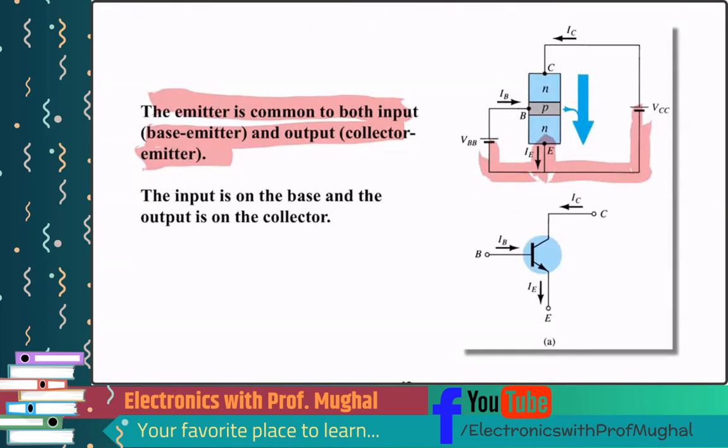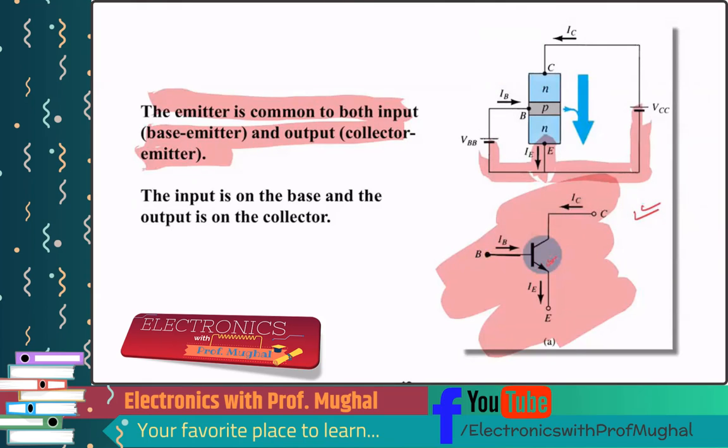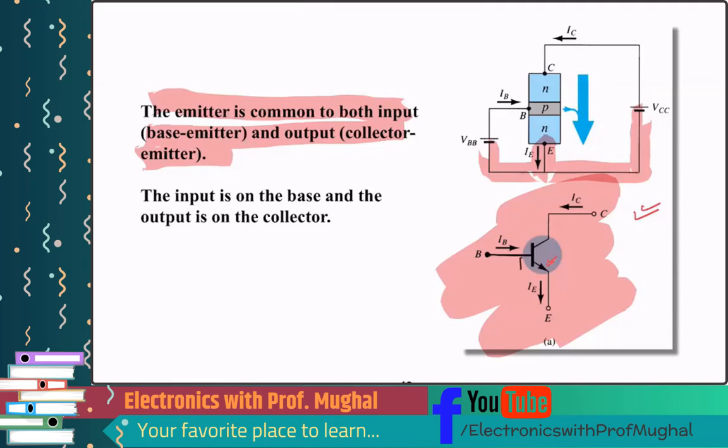Okay, how would you put it in a schematic? Well, it's going to look something like this. If I ask you whether this is a PNP or NPN transistor, what is the direction of this arrow? It's pointing downward, correct? Therefore, is this base P-type or N-type? P-type, because current always flows from positive to negative terminal. And if this is positive and this is negative, then surely this terminal, which is the collector, is going to be N. So this is an NPN transistor. And if you notice, this is also NPN over here.